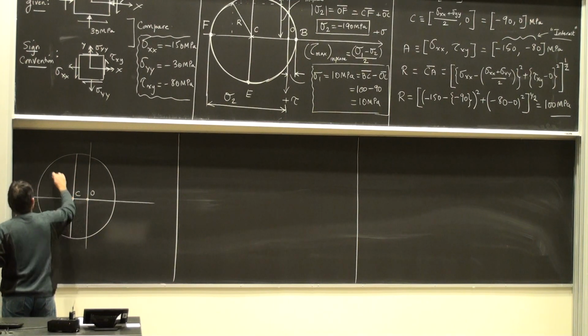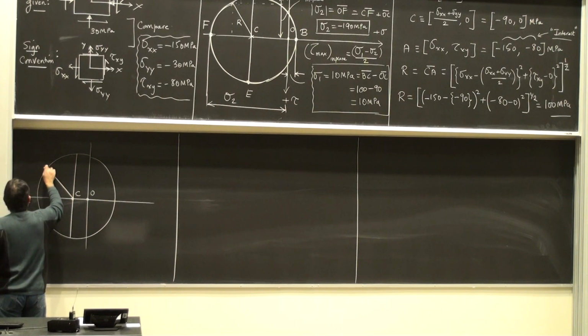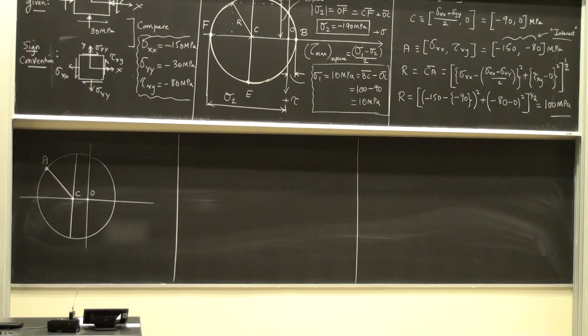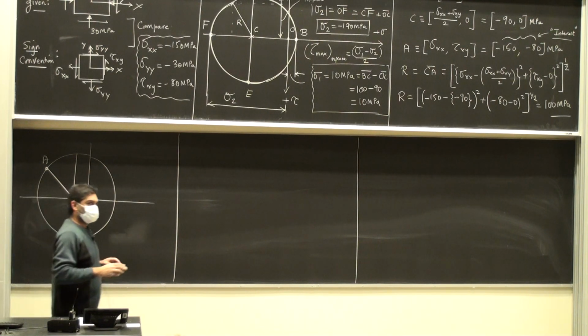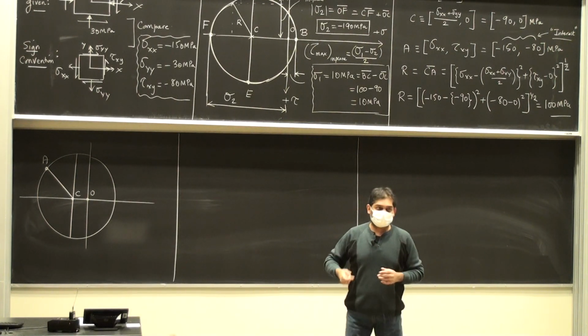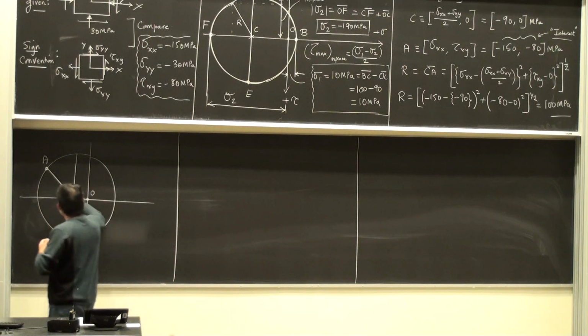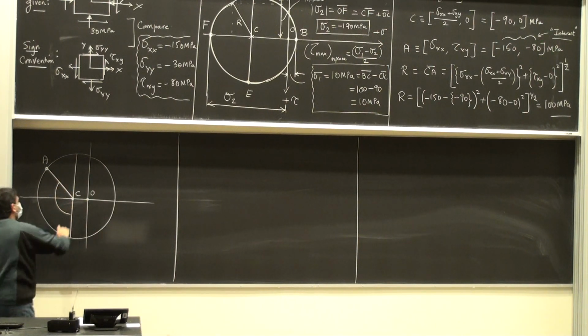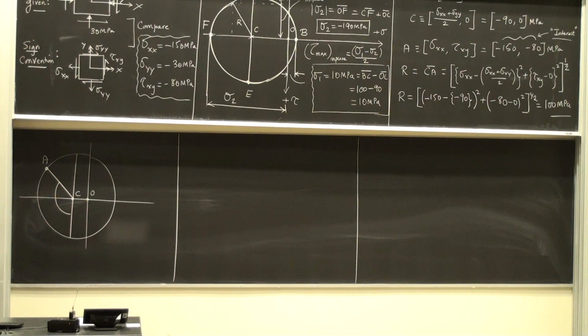Point C. Pointing. Okay? Alright. To draw the shear plane, should I go counterclockwise or clockwise? Let us start off by going counterclockwise. Okay, so I go from CA all the way to the first maximum shear stress value that I reach, which is right here.